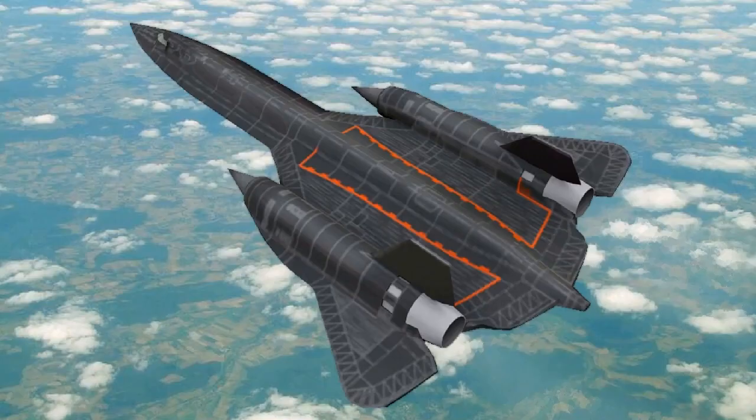At very high speeds, the aircraft obtained 80% of its thrust from the ramjet operation, as opposed to 20% from the engine operating as a turbojet. This improved the specific fuel consumption figures by between 10 and 15%.